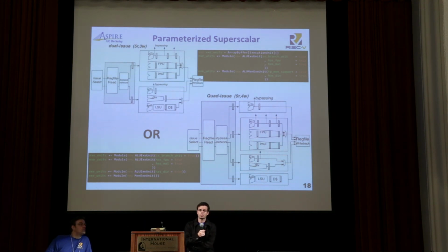Right. So when we have a chip generator, you can only verify what comes out of the generator. You don't try and verify earlier. For something like the clock frequency, I'll pick a design, throw it through, and hit on the critical path. Right now, I've been paying most attention to the dual issue, making sure that runs pretty decent. The 4 issue, I've not had enough time. That's not going to run at 2 gigahertz. But typically the SRAMs are pretty slow, so you can hide a lot of logic. But yeah, if you do 4 wide, there are other things that you might have to shrink in size.